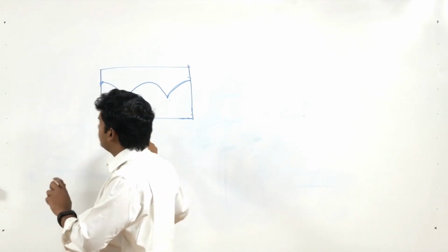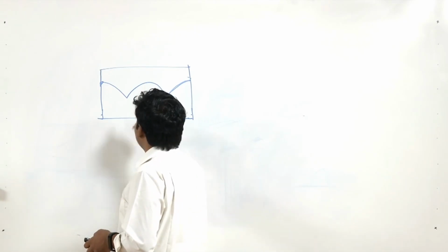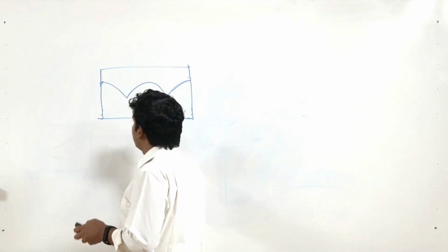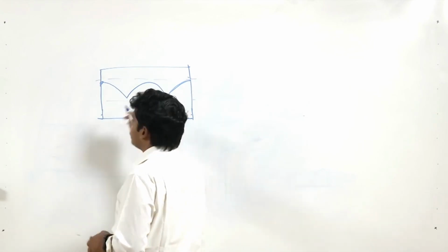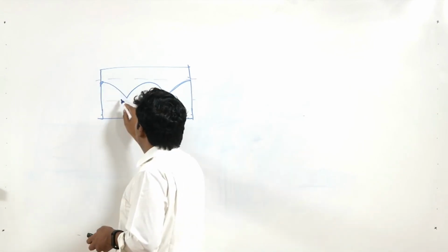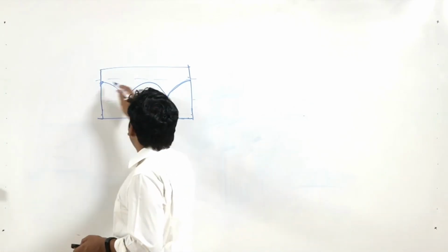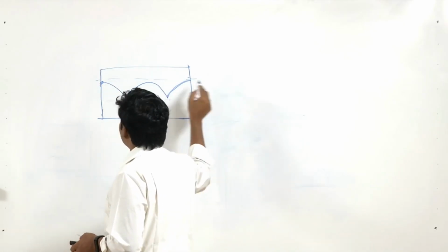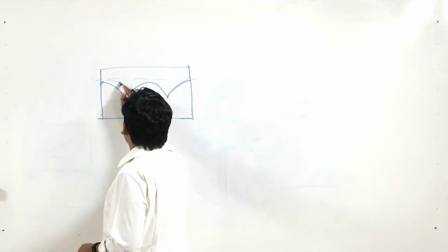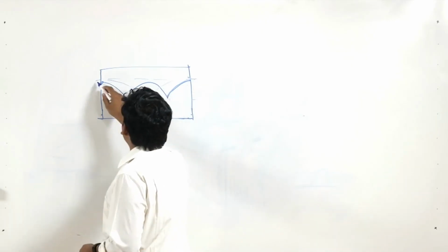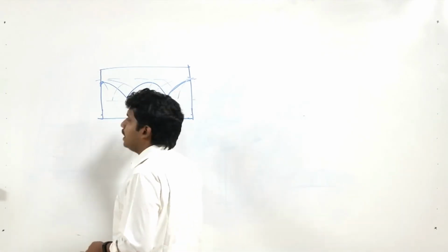There is a separate set of cross checking that you need to do. Depending on those things, you will be able to find whether room mode would occur in a particular space or not. In this case, a particular set of waves at a specific frequency might develop a standing wave. A standing wave is something which is perfectly fitting peak to peak here. It may be 1, 2, 4, 5, as many as certain numbers. It may be just one wave, or it may be more, but they do not decay easily.